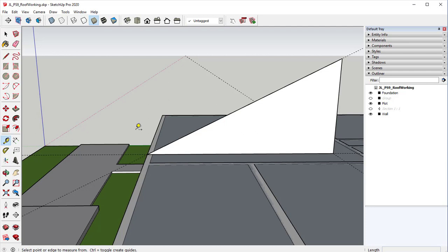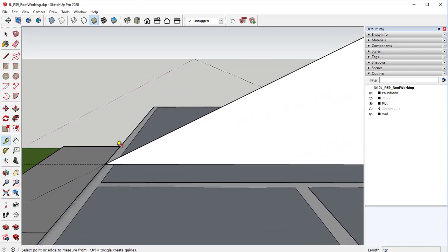We're going to take our tape measure and finish up drawing how our roof looks if we cut it in half. Our roof right here, for us, is going to be a 2x6, which is what our roof is made up of. So I want to take my tape measure, make sure it's going down, and hover over this inner part of my wall. It comes up to going down 1 and 13/16 of an inch.